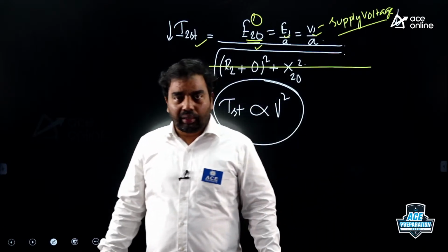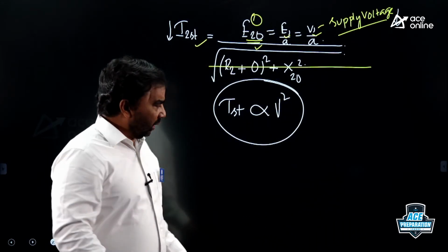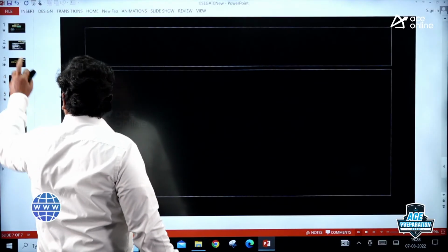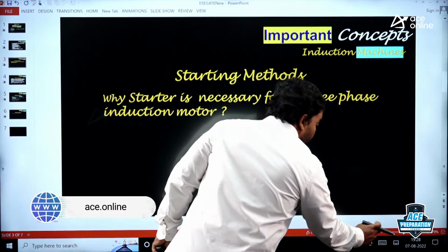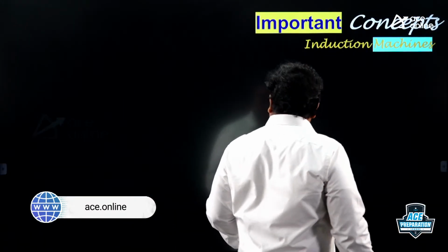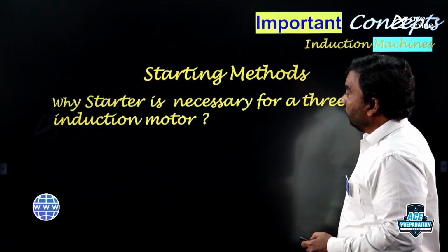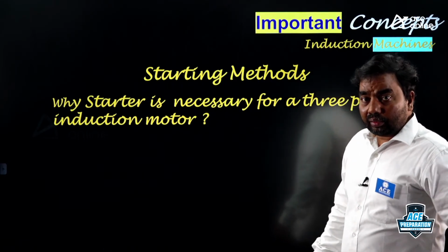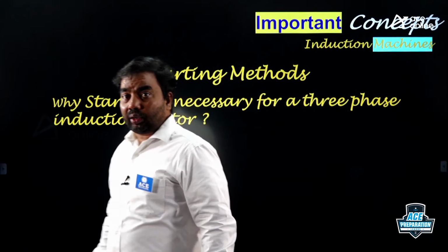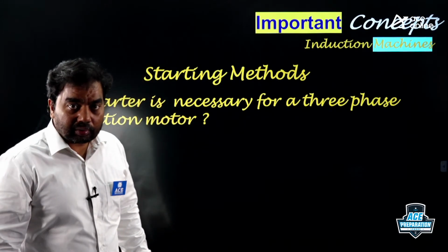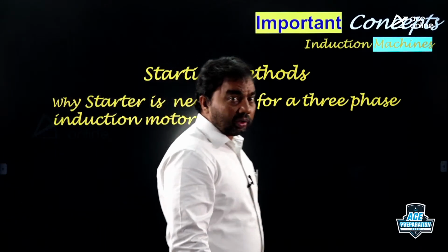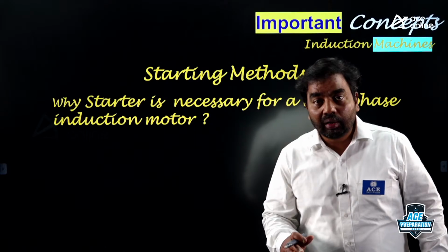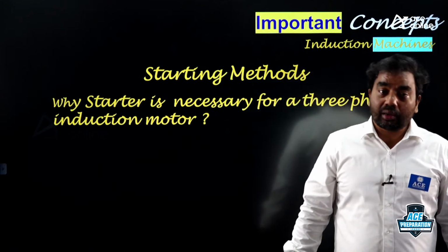So finally, can I say like this? Why starters? Why is a starter necessary for a three-phase induction motor? I can say the purpose of a starter for a three-phase induction motor is not for starting the motor, as a three-phase induction motor is a self-starting motor. But the purpose of the starter is to limit the high inrush of starting current.